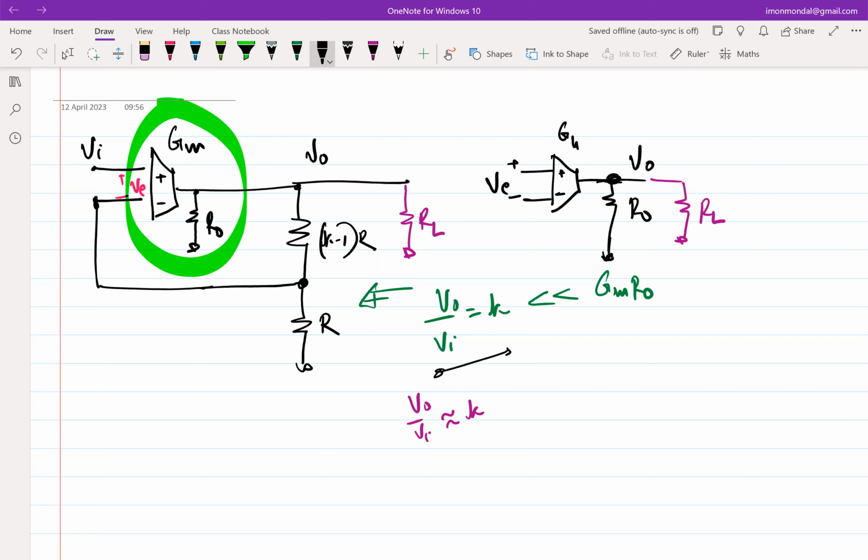So when you are using your electronic devices or any devices for that matter, you want a predictability in their performance. You don't want it to behave like something today and something tomorrow, or if the temperature changes or humidity changes and so on. So predictability, reliability is a very important aspect of any engineering system, and negative feedback helps us in achieving that. Now, one of the reasons this negative feedback works is you need high loop gain, right? You have a very good error amplifier which can kick the loop in the right direction in case it diverts from the direction of choice.